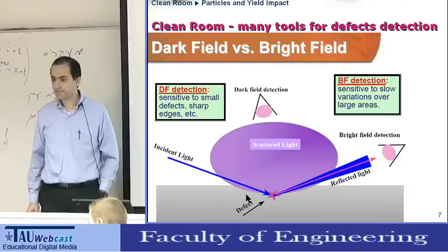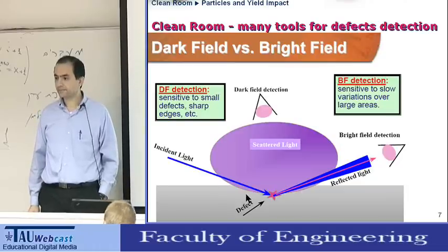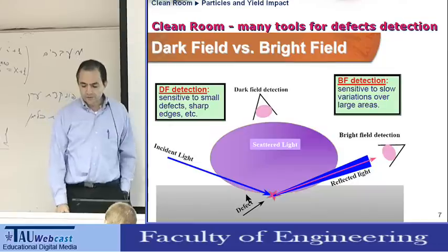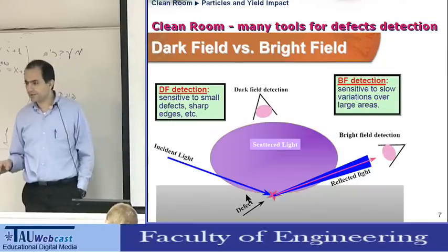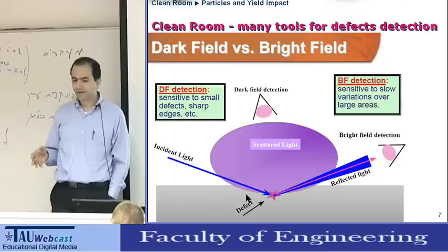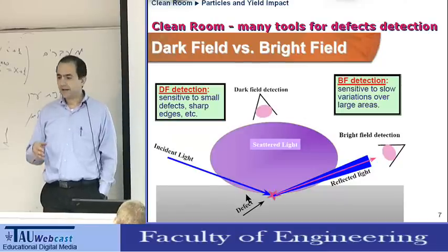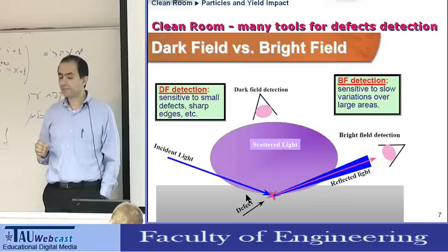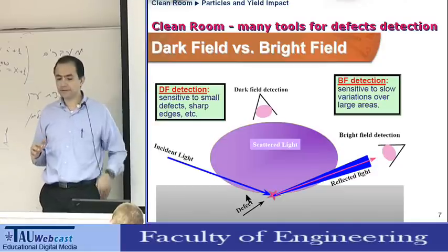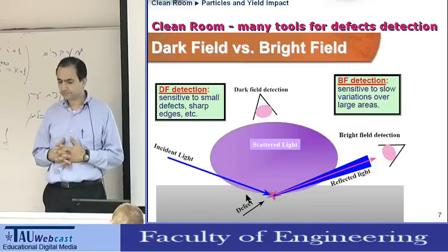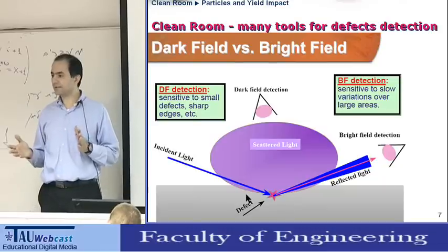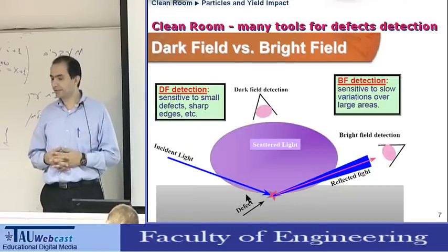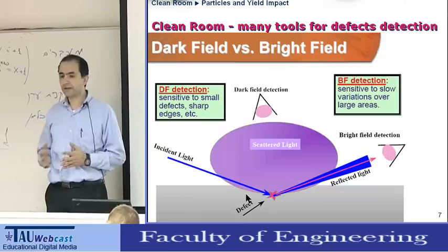Yes? Every process, every chip will go through this phase, or it's just randomly checked, like one in 10,000? So this depends on the fabrication facility and the exact methods. And at several steps in the line, the wafers will be checked. Usually, just a few wafers from the lot. Say a lot has 25 wafers. Rarely more than 5 wafers will be checked, typically between 1 and 3.